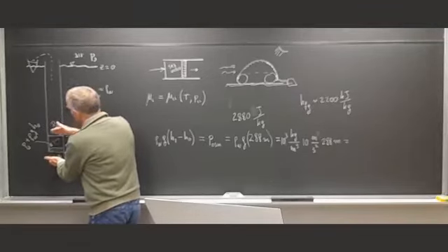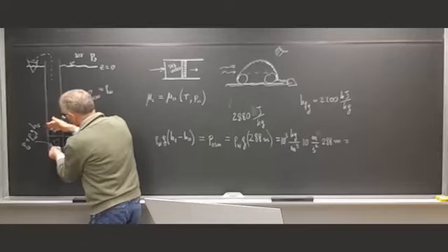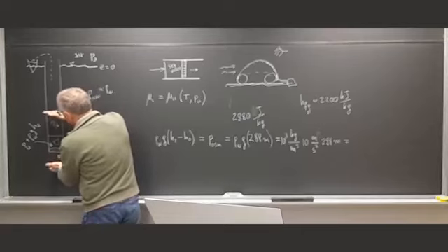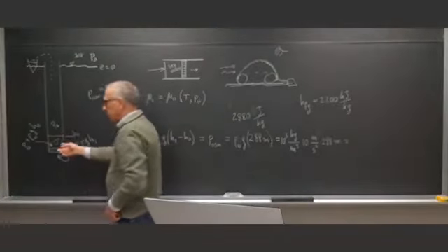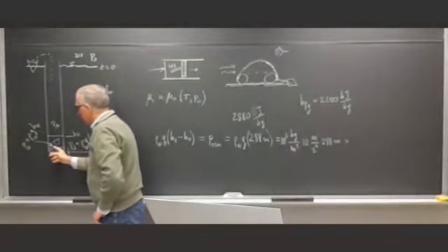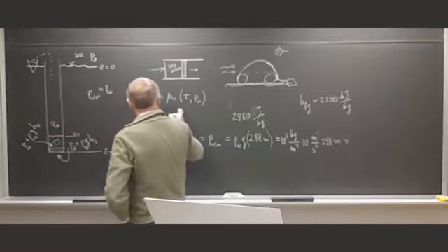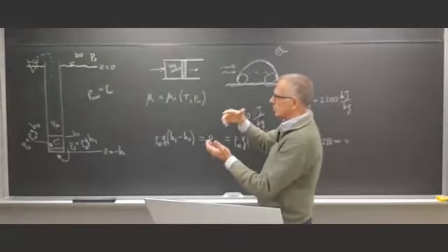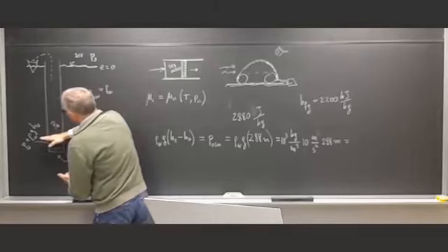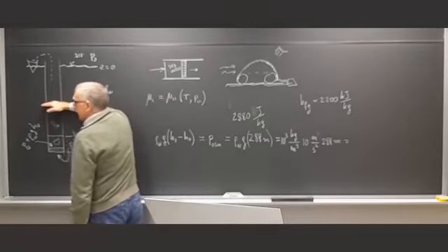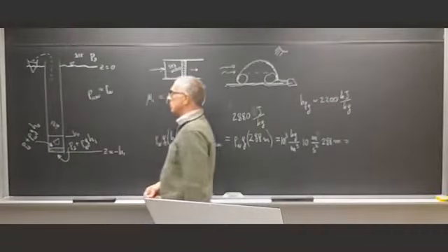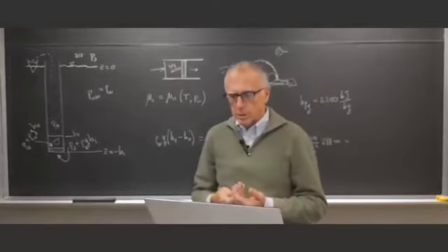And I don't need a big difference in pressure to make it flow. Of course, I do need some difference in pressure, otherwise the flow will not be able to win the pressure drops in the porous plug. So I cannot obtain 100% of this. That would be a zero power situation. If I need power, I need to do it at a certain rate, so instead of being here, let's say being halfway, I use this much head in order to push the fresh water into the sea. In any case, this is what is called blue energy.